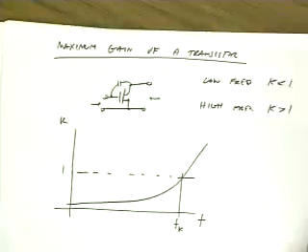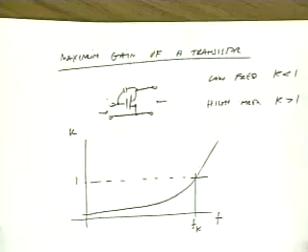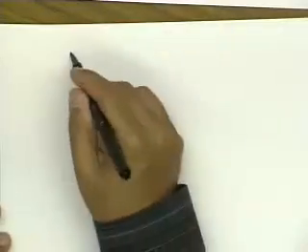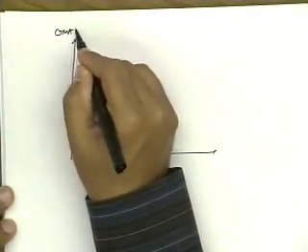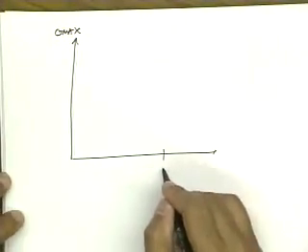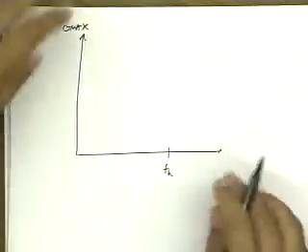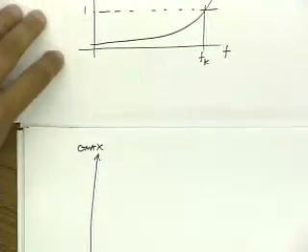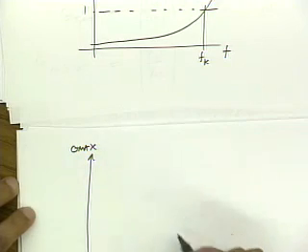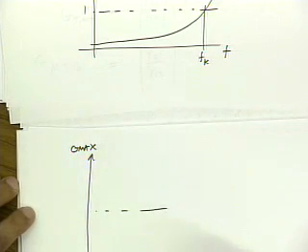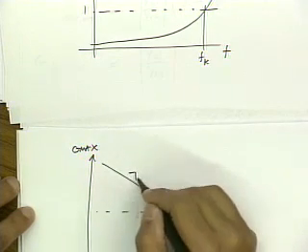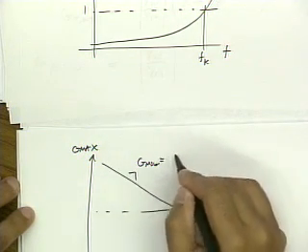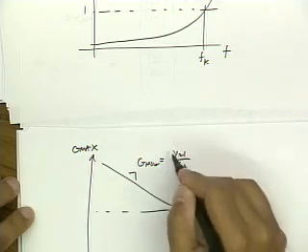Now if I plot the maximum stable gain I can get from my device, let's call this Gmax, then up to the knee frequency, it's unstable, so I have to use the expression GMSG, which is simply y21 over y12.